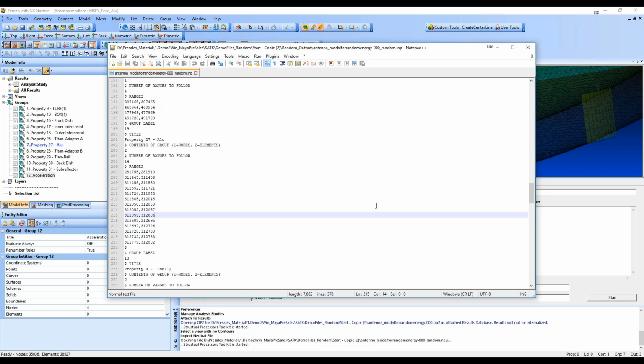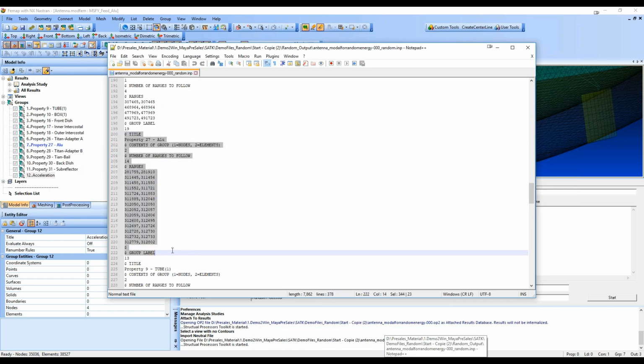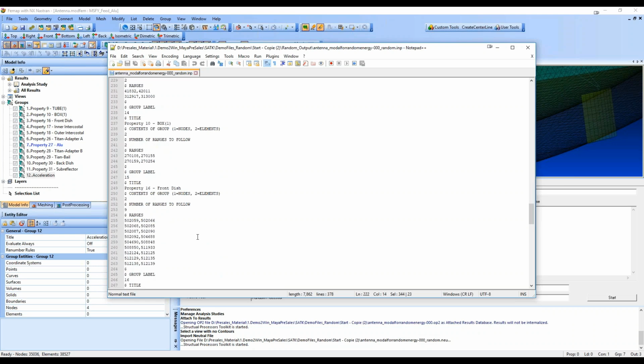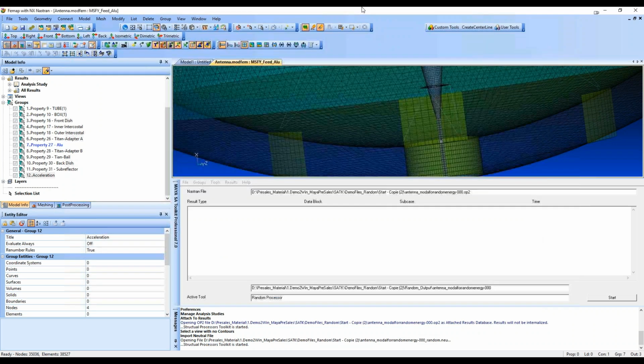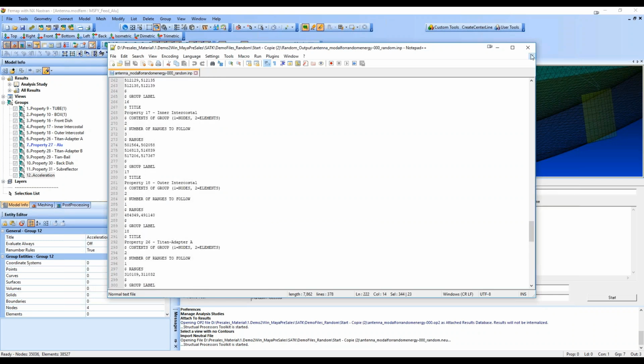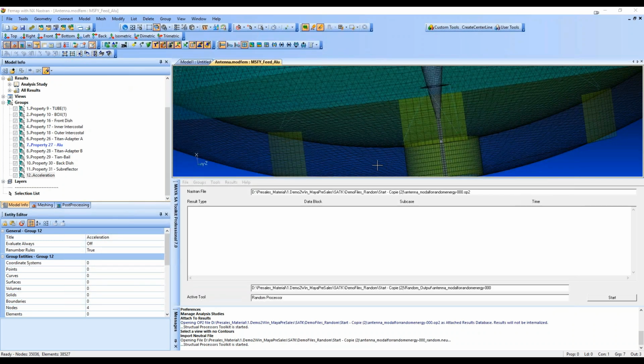We've defined the stress cases manually at this point, but the stress cases are nothing else than just this. So what you'll do is just copy a stress case or write it from scratch and just add your own allowables for each. So again, it can be done inside or outside. Can you read in multiple inputs to create multiple cases, or do you work on one input file at a time?